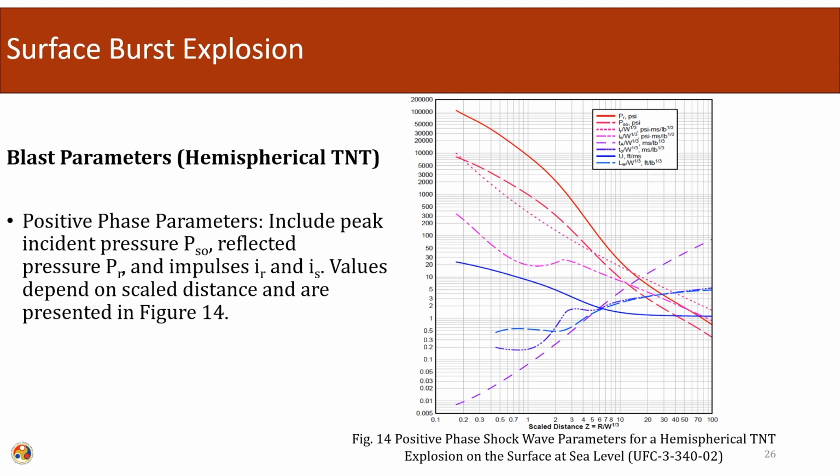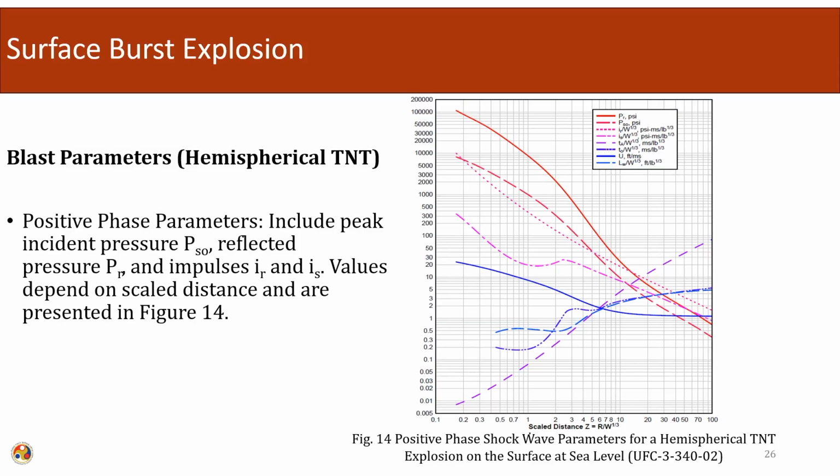So, blast parameters. Similarly, as in the case of air burst, using the same principles and the same established equations, we can calculate the different parameters associated with the blast loading. We will use the same parameter, the scale distance Z, which is made up of standoff distance and the equivalent TNT.